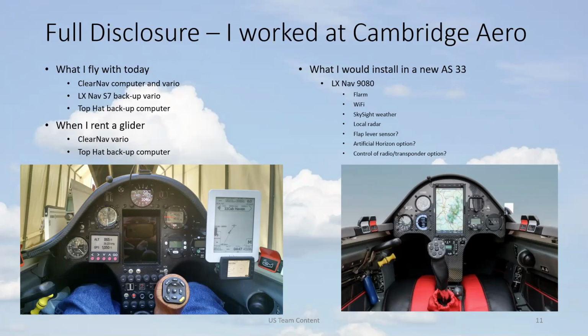When you're on the ground and the whole thing's in the sun and the canopy's closed, then the temperature goes way above 40 centigrade, and then they become a problem. Yeah, I've seen people put a small towel over the top of the flight computer if it's on a RAM mount, just to keep it out of the sun while they're doing something. But I haven't seen any need for active cooling.